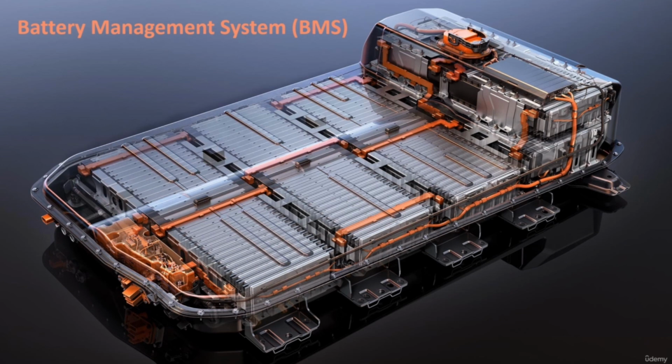This is to prevent individual cells from being at a relatively high or low state of charge, which exposes the electrolyte to relatively large overpotentials. As discussed, this may lead to electrolyte degradation, one of the major contributions that shorten the cycle life. There are several ways to achieve balancing, where a sophisticated approach is to shovel the energy from the higher charged cells to the least charged cells. In this way, the BMS is vital to achieve a long cycle life of the battery pack in combination with providing optimal performance.